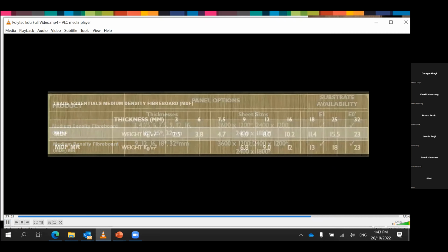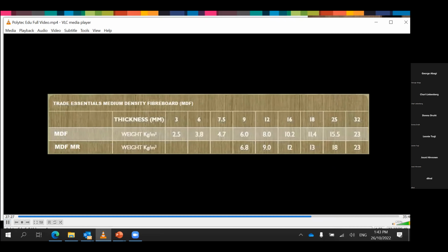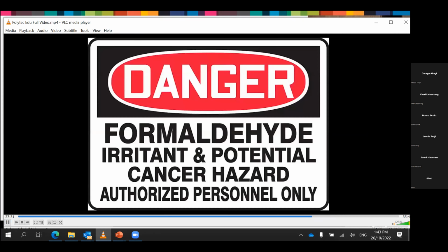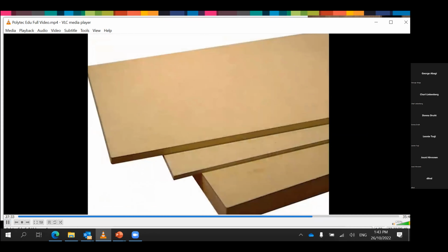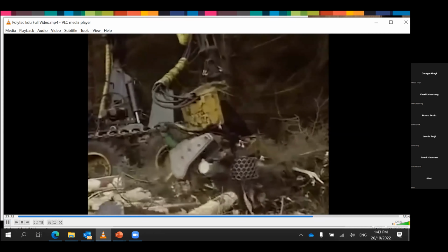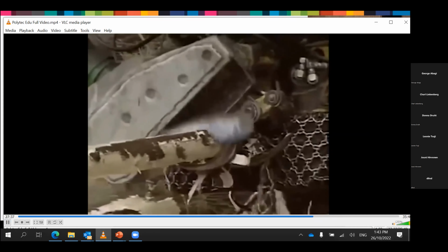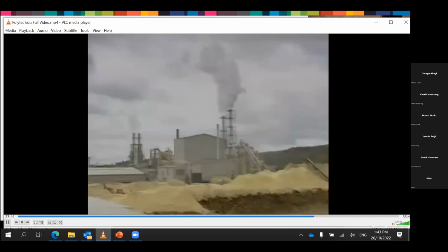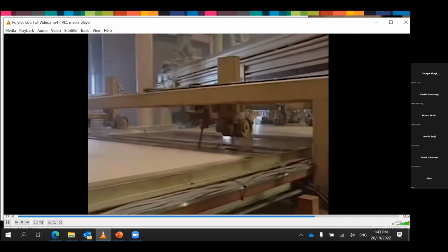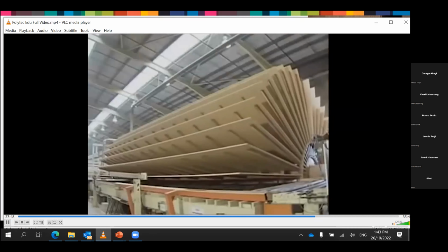Scheme, or laboratory testing in accordance with Table 13.2 formaldehyde emission limit values for engineered wood product. Medium density fiberboard, or MDF, is an engineered wood product formed by breaking down real wood, Pinus radiata, residuals into wood fibres and glued back together with special resin by applying high temperature and pressure.